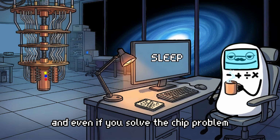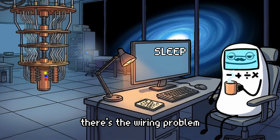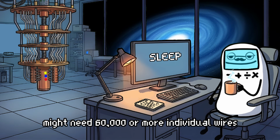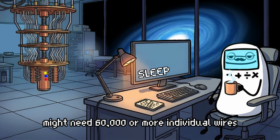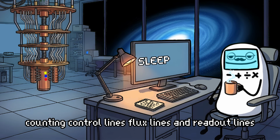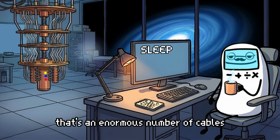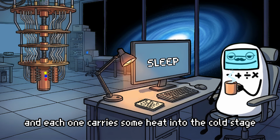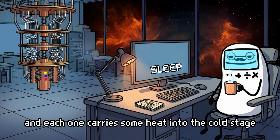And even if you solve the chip problem, there's the wiring problem. 20,000 qubits might need 60,000 or more individual wires going into the refrigerator, counting control lines, flux lines, and readout lines. That's an enormous number of cables, and each one carries some heat into the cold stage.